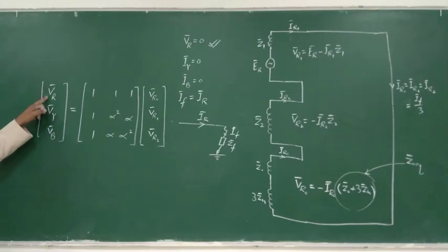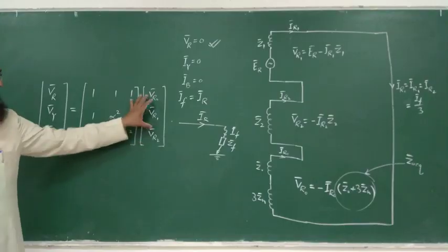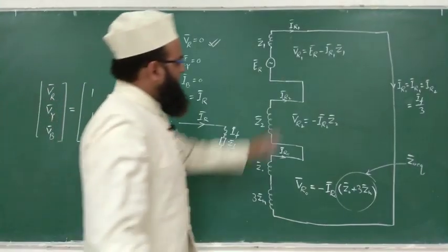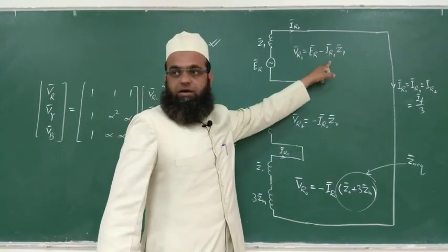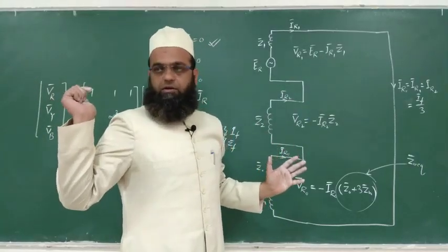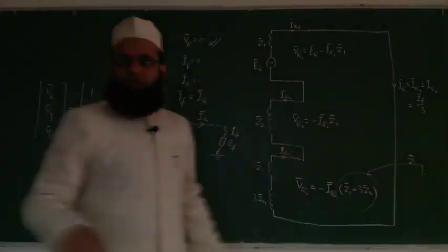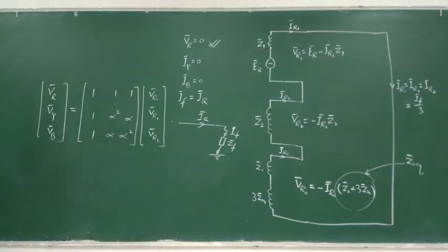What is VR? Okay. So if you have not considered ZF, fault impedance, in that case VR was 0. So whatever the values will be there, you will evaluate VR0, VR1, VR2. So algebraic sum must be equal to 0, just check it. So VR1, VR2, VR0, just add together, put the values of IR, that is EF upon something, Z1, Z2, Z0 equivalent, whatever we evaluated, right? So you will get 0, just check it at home. Fine? Any question till now?